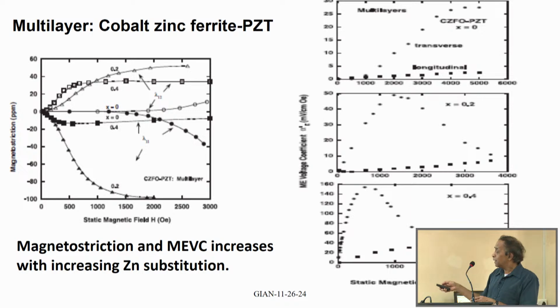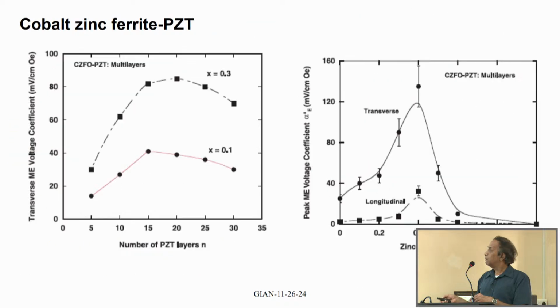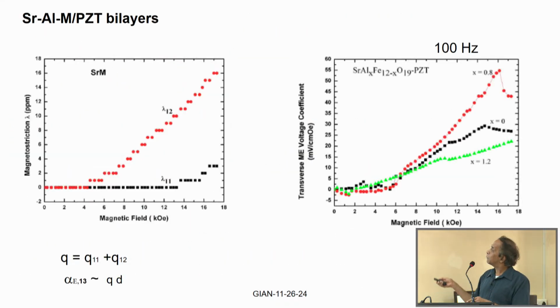Something like this, you cannot put together a sensor of DC field, because at high DC field, the voltage coefficient goes to practically 0, and you cannot make a sensor out of it to measure the DC field, whereas looking at this response, it's rather easy to put together a calibration chart, ME voltage versus bias field. Then you should be able to use this calibration to determine any unknown DC magnetic field.